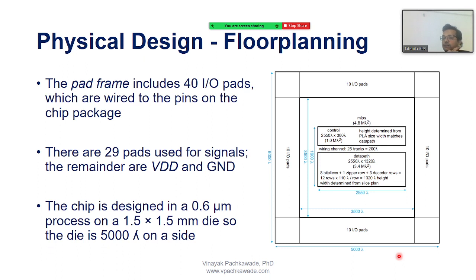So you see what was the lambda rule for the CMOS inverter layout? I explained to you, that's equal to L by 2. I told you, lambda is the process parameter that helps us to estimate the cell size that we are designing or drawing using the layers in a given technology.